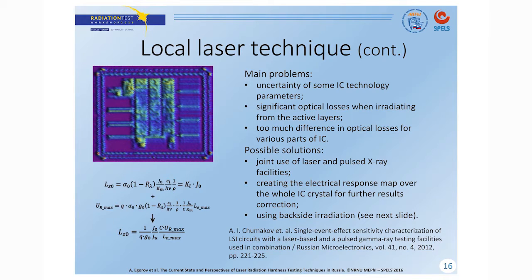The following problems might arise in this technique: the uncertainty of some IC technology parameters, significant optical losses if we irradiate from the active layer side, and too much difference in the optical losses for various parts of the IC. And here are possible solutions for these issues.